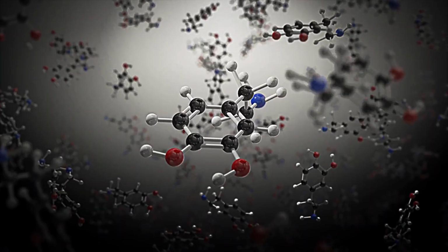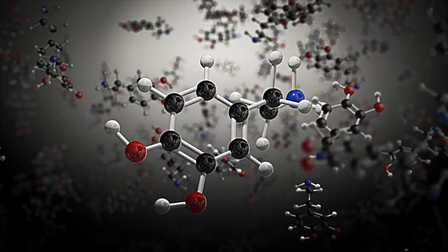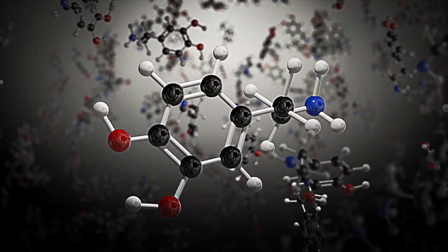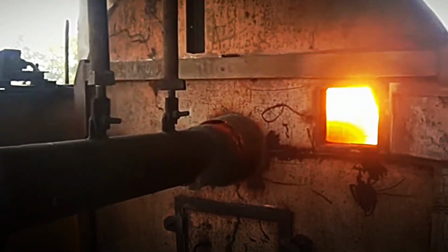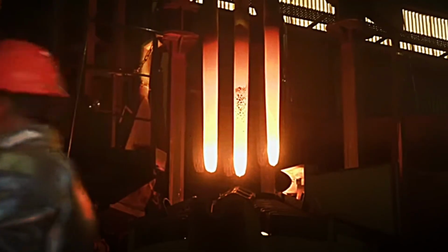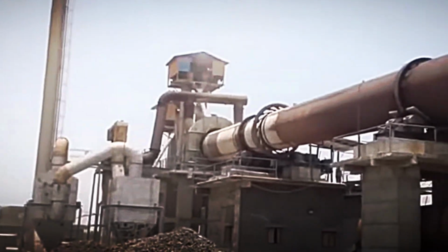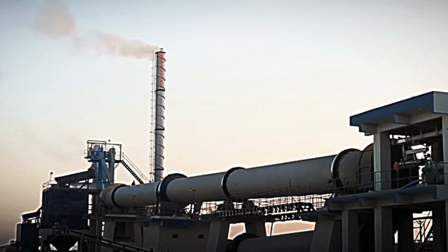To achieve this, small particles called seed crystals are introduced. These act as nuclei to which new aluminum hydroxide molecules adhere. The process takes place in giant tanks with trays and controlled agitation systems. Over time, the seeds grow into larger, purer crystals. Once they reach the desired size, the crystals are separated from the remaining liquid. This step is vital because it ensures that the final alumina has a purity level high enough for the next stage.